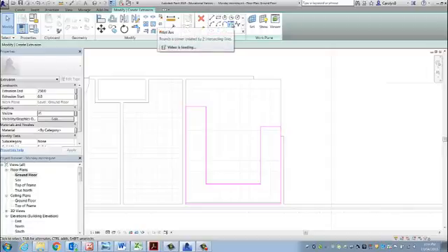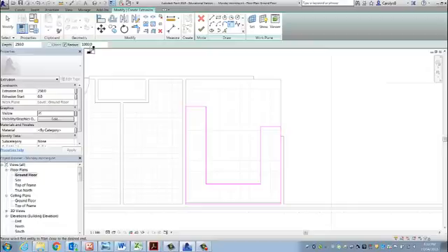This little tool in here is called a fillet arc. It's in the draw tool, not the modifier. You've got to hover over it to find it. And when I click it on, I can check radius. And I'm going to tell that radius to be 200. I'm going to create the curves on the edge of my bench. Very 1980s.